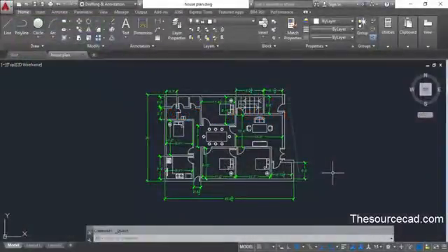Once you've completed your drawing, you need to get your output in paper format. Before getting your output, you need to arrange those drawings properly with all the information like scale, layout, sheet number, and other information. Those informations are added in the title block of a drawing. AutoCAD offers some standard title blocks for you, and those title blocks can be inserted in a drawing from templates.